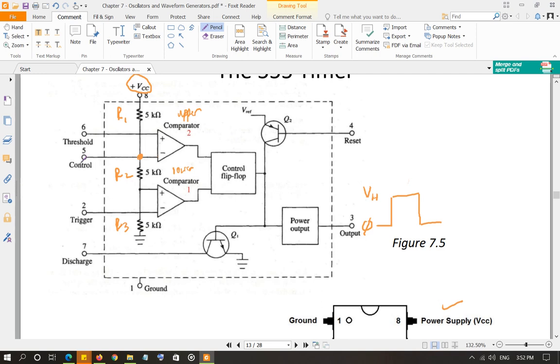Now, why are they grounding it through the capacitor? Because of course a capacitor blocks any DC voltage. So it's going to block that ground, so the ground is not going to appear over here. Otherwise this pin is going to be ground. Any DC quantity, that DC signal or DC current coming from the ground, the capacitor is just going to block everything from there.